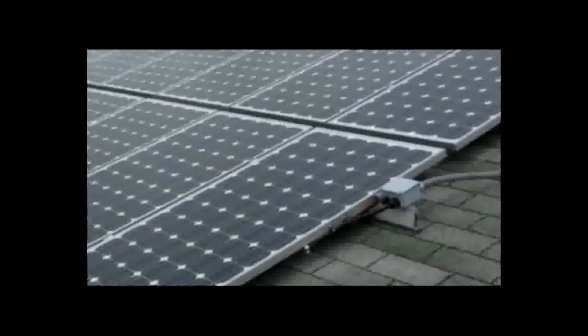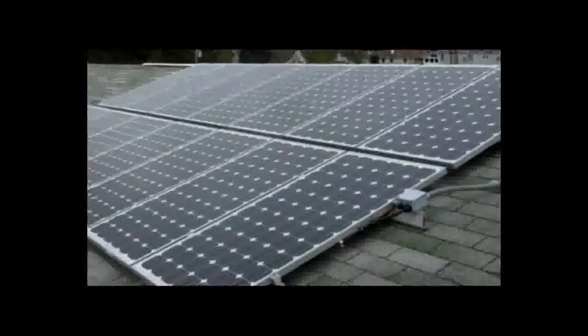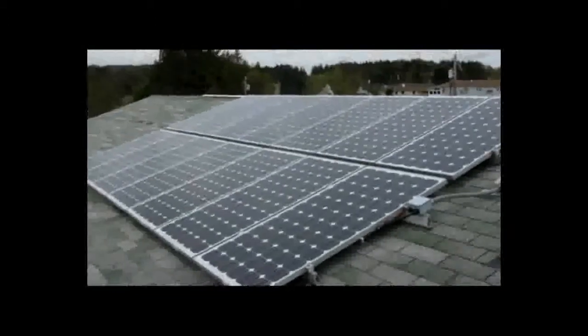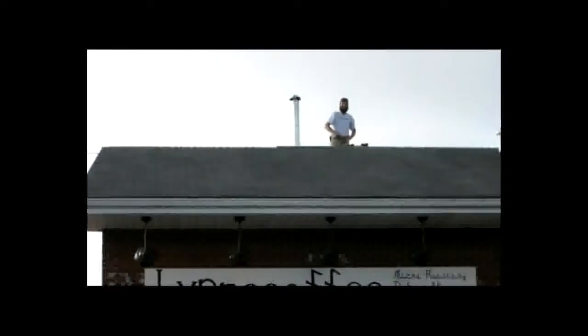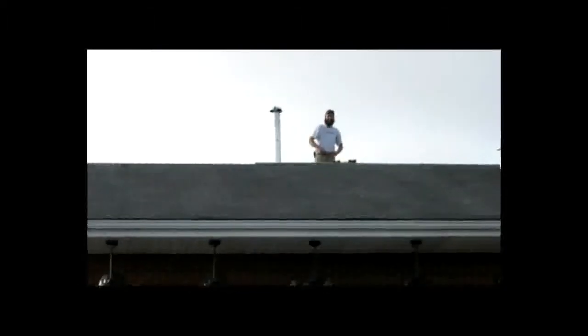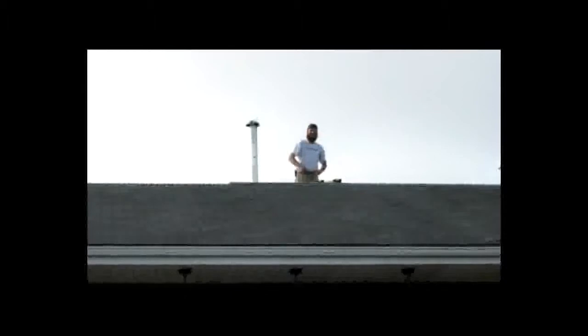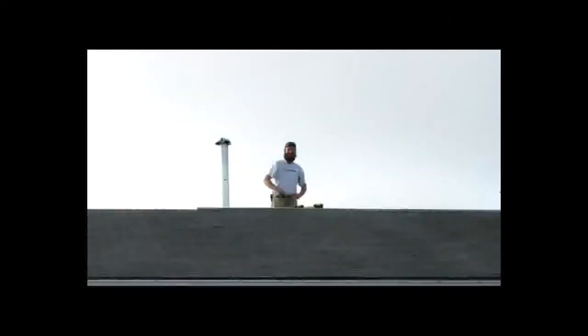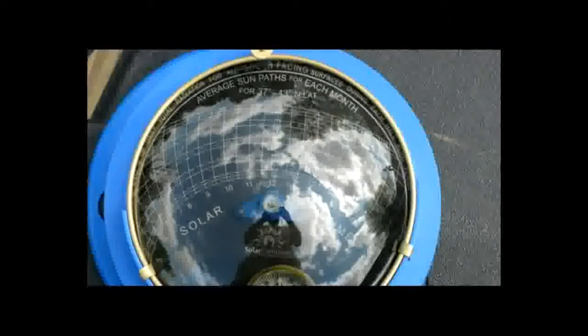That's like having 2 microwaves turned on and feeding into the building instead of drawing power. And that's what the nameplate rating for a solar electric system means in terms of how much power it can produce. Now, as the sun moves away from noon and down closer to 4 and 5 in the evening, it'll stop making its nameplate maximum, 2,400 watts, and it'll make something less than that.